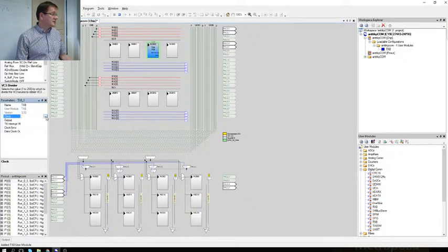Then we just need to set the clock as VC3. Okay, the bit rate actually is always the clock rate that comes to that module divided by 8. Because of synchronization reasons, the input clock rate for this module must be 8 times faster than the transmission clock rate.